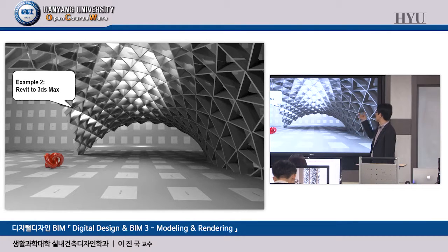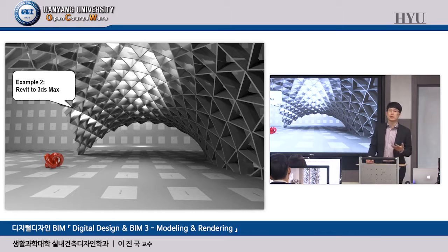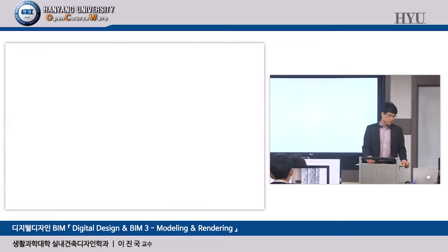Unfortunately, the depths and the part geometry couldn't be controlled in this 3D Max, but if you have the family file, the Revit file, and the Revit model, you can control the part geometry and the surface geometry. But anyway, the project surface scale, location, angle, some geometric aspects, of course, are free to edit in 3D Max. That's my point. They are lab exercises number 5 and 6, okay?